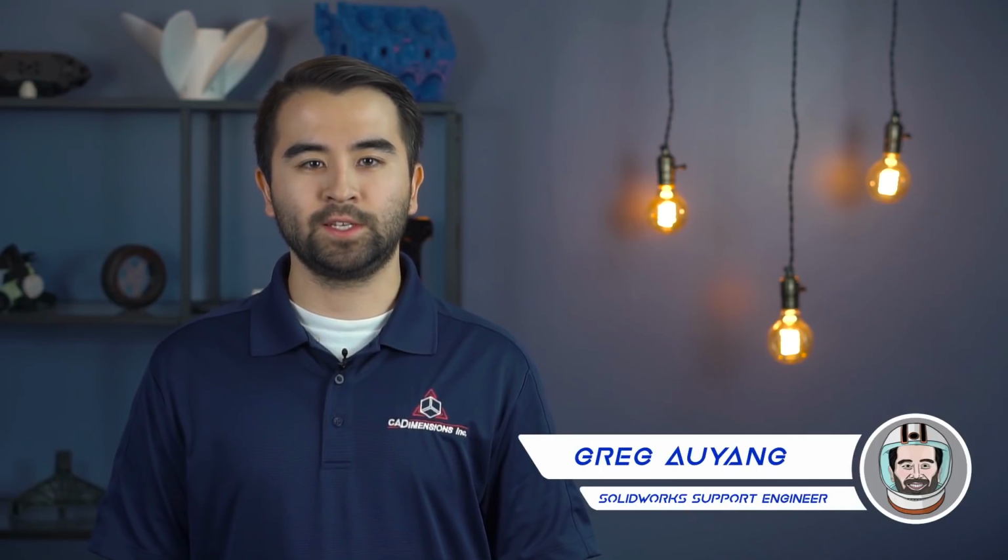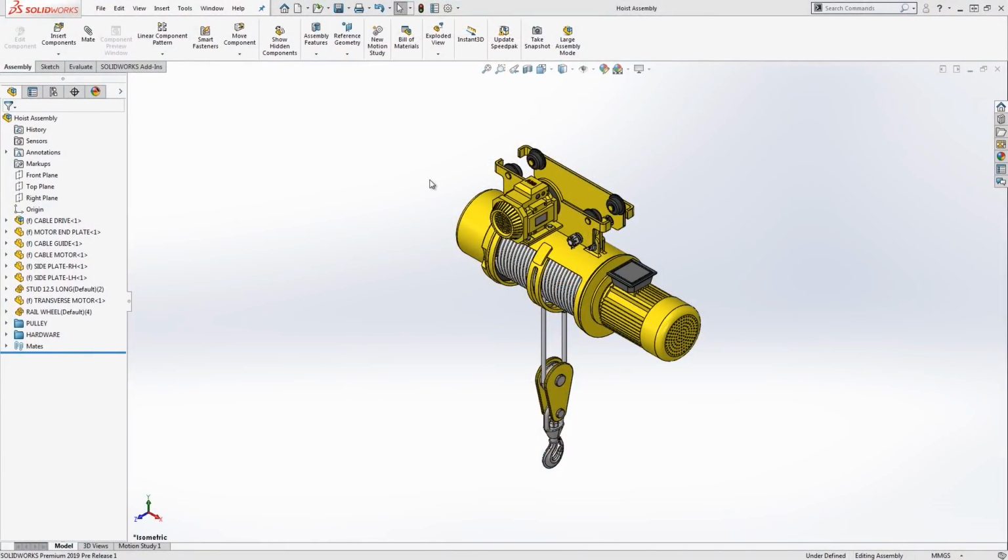Today I'll be showcasing some of the new enhancements to the SOLIDWORKS 2019 user interface. I hope you all are just as excited for the new enhancements as I am, so let's go ahead and get started. Breadcrumbs have been modified to make your job even easier when working within an assembly with multiple mates. Previous versions of SOLIDWORKS only allowed for one mate to be selected from the breadcrumb selection box. However, new enhancements have been made to speed up the process of editing current existing mates. In SOLIDWORKS 2019, you can now select multiple mates within the breadcrumb selections and make further edits or changes to